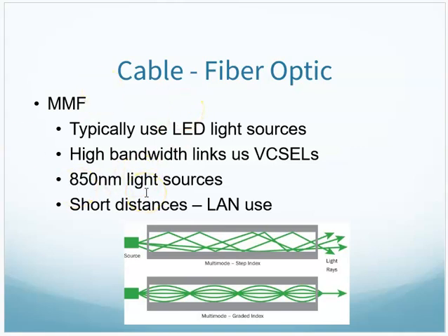Your multi-mode fiber, again, is typical LED light source. 850 nanometer light source, the wavelength of light source. This is typically used for short distances for LAN use. And we're talking hundreds of meters, not thousands of meters.